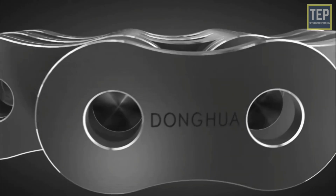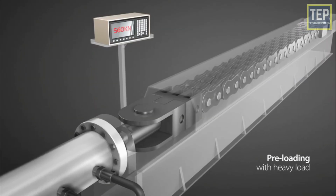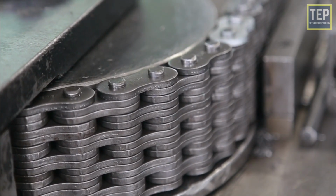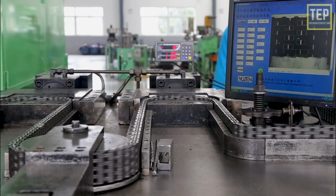Leaf chain is the most simple of steel chains, consisting only of link plates and pins. This chain generally has greater tensile strength than roller chains and runs over sheaves, rather than sprockets. They are suitable for hanging, balancing, or motion transmitting applications.